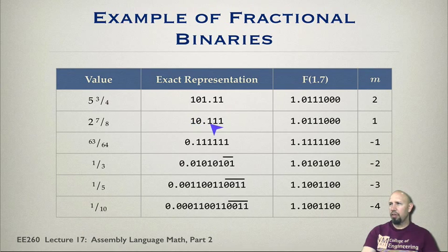If we notice, this is now the fixed point 1.7, where I have 1 point to the left, and then 7 to the right. So altogether 8 bits. That's part of the reason why F1.7 is used. The 1.7 refers to the fact that we have one bit to the left of the radix point and 7 to the right.